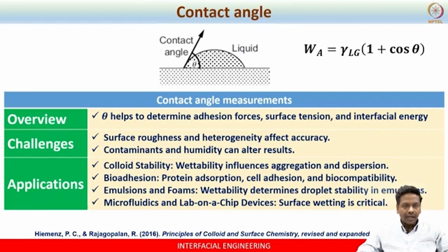Okay. Again, based on the Young-Dupre equation, this one you will be familiar because we have developed this equation during our module 2. So by knowing the theta of the liquid, okay, contact angle established by the liquid with the surface, you can calculate the adhesion strength or adhesion force, I mean adhesion energy in this case. Okay. For that, you need to know what is the gamma Lg component of the liquid that you will be dealing with. Okay. And this is very easy to obtain, right?